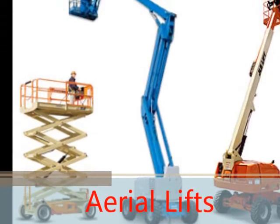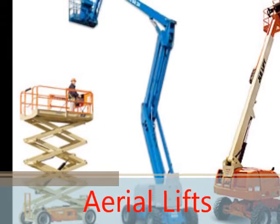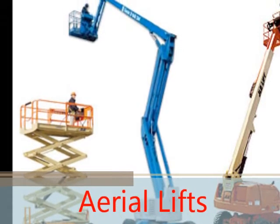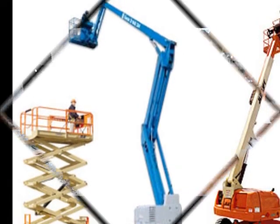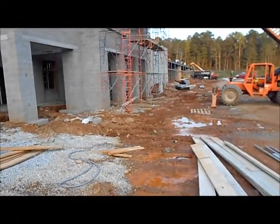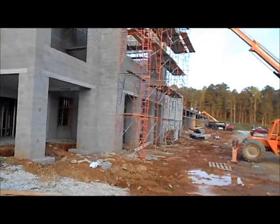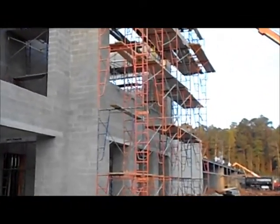Lastly, we will discuss aerial lifts. These are also known as cherry pickers, boom trucks, or man lifts. Before using an aerial lift, you must inspect the ground and all overhead areas. You must be on a level surface, and it is best to move with the lift down.